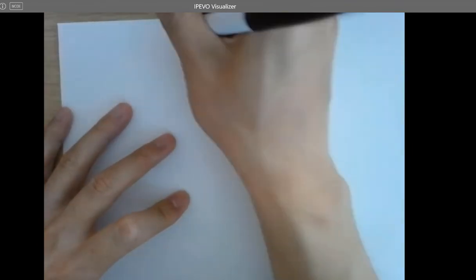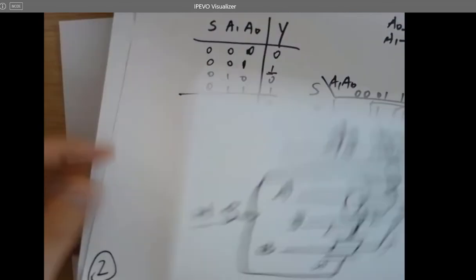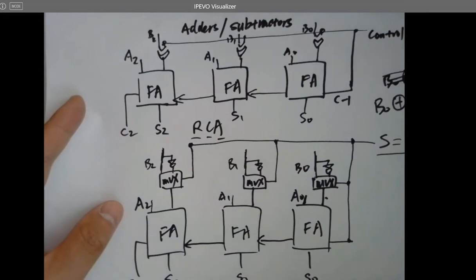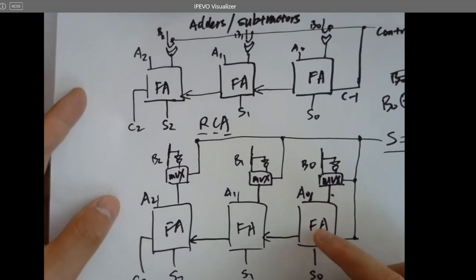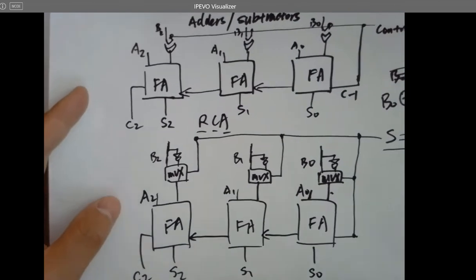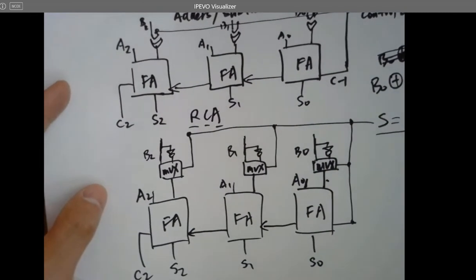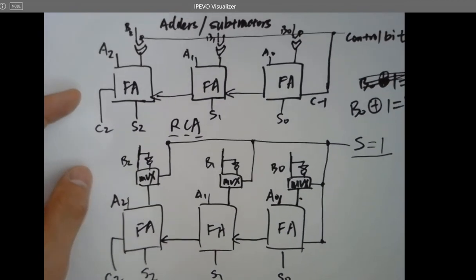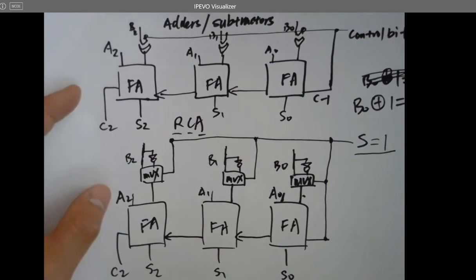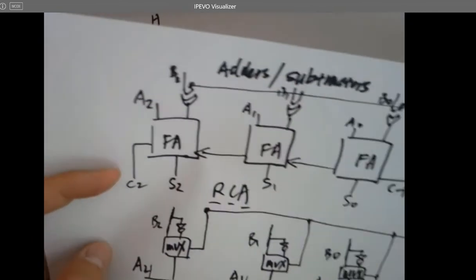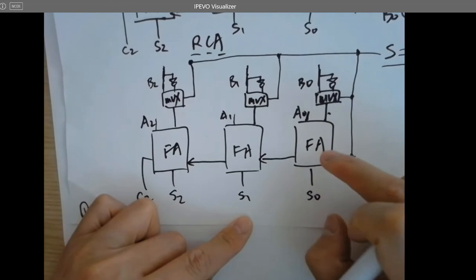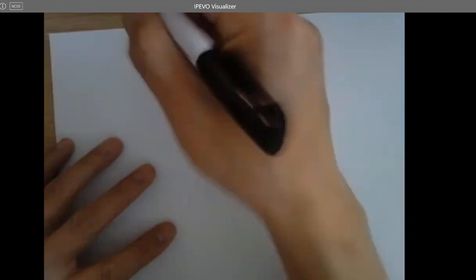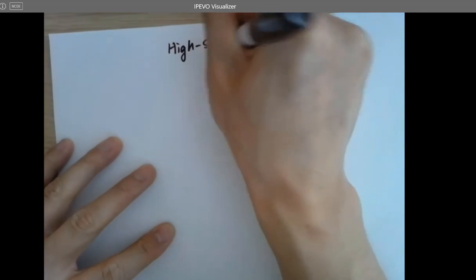Now let's look at the high-speed adder. Because we are designing this part, right, so this subtractor right now, and we know how to design the compact MUX already, we're going to use the transmission gate to form this guy. The full adder is still huge. So we have XOR gates, we have all the other things in there. We know how to convert an AOI logic into complex CMOS logic gates. Right? We can directly find out the logic expression and figure out the simplified version instead of just using logic gates. Right? We can optimize the circuit structure. So we know this, and now let's design this one. So the overall adder subtractor will be way more compact than the traditional one. This is called a high-speed adder or high-speed full adder.